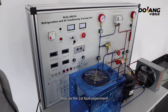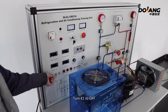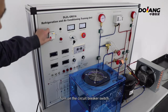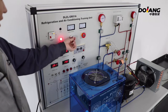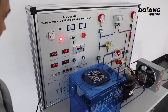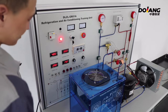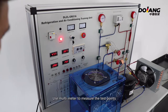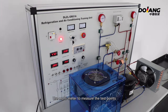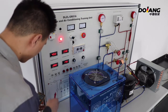Now do the first fault experiment. Turn K1 to off. Turn on the circuit breaker switch. Turn on the key switch. Press the controller switch. Then press the switch on the remote controller. No response. Use a multimeter to measure the test points. Turn the multimeter to the AC 220 volt gear.